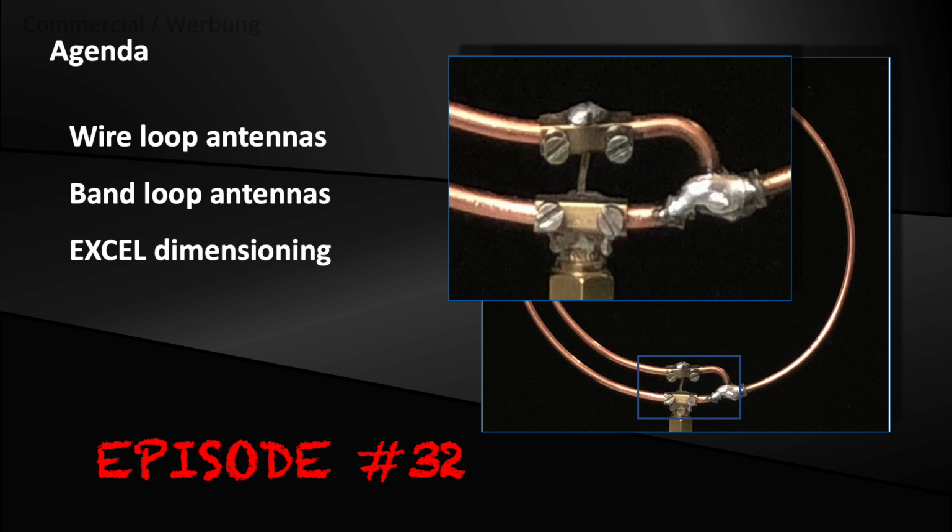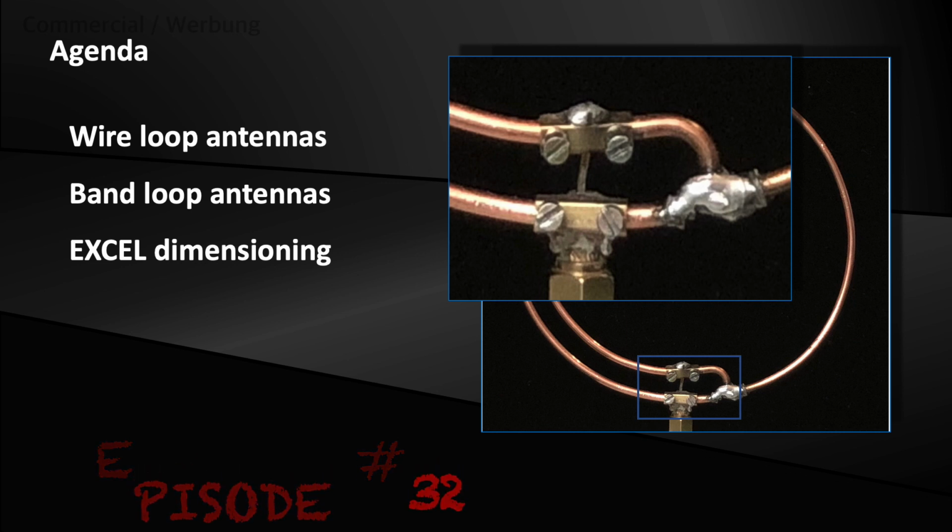The loop antennas described here should not be confused with so-called magnetic loop antennas, which are often used in amateur radio. The circumference is exactly one wavelength, so they become relatively large at low frequencies. Magnetic loop antennas are much smaller, so please do not confuse.